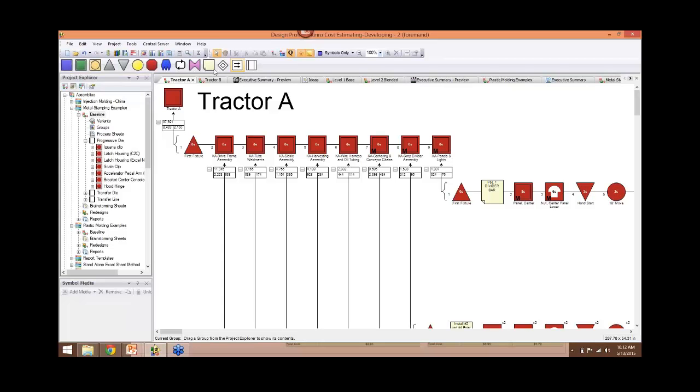So you'll see symbols at the top of the software. They represent parts, sub-assemblies, pre-processed parts, and the tools you need to build it, whether it's a fixture, a hand screwdriver, a power screwdriver, or an actual stamping press. Fastening is how you actually fasten, whether you're screwing a part in, welding it, or using gross deformation. Then there are all your secondary operations, machining processes, inspections, and options, so that if we have more than one way to do the job, or more than one option like seat color or other implements. And then parallel activities, where we can model multiple operators working within the same cell.